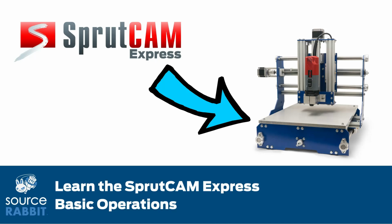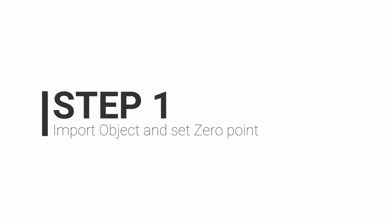In this tutorial, we will show you how to use the basic operations of SprutCAM Express and generate G-code for your CNC projects. It is a simple 7-step process that takes only a few minutes to watch, so let's start. Step 1. Import object and set 0 point.